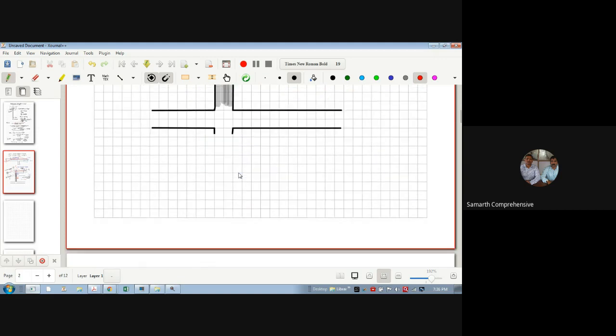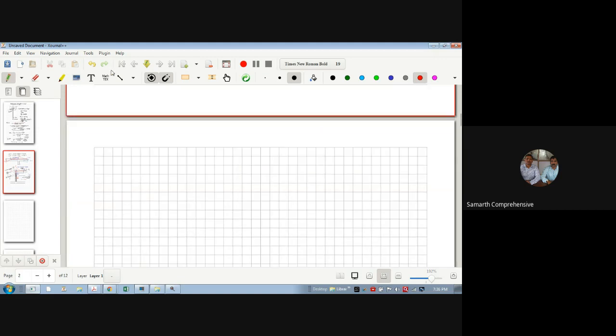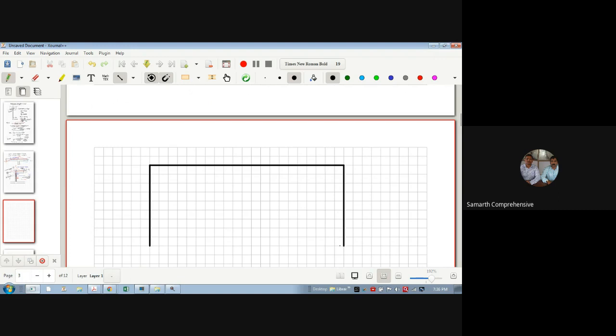And we also provide LD in fixed beams. So fixed beams generally, I want to tell you one thing. Whenever we design any beam, if your beam is resting on the column, then we generally design the beams as fixed beams, because the columns are already there who will take care of the moment, so there is no problem.